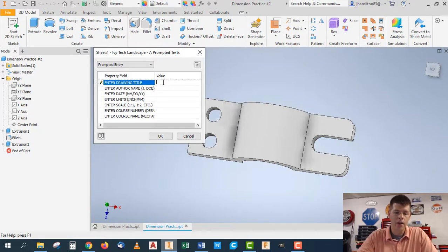So use all caps on your drawings always. This seems weird to people now because of social media and texting. People look at all caps as screaming or impolite. Remember that all this technical drawing stuff predates current technology. So back in the technical drawing hand drafting days, everything was done in caps because it was easier for the drafters to mimic each other's handwriting styles.